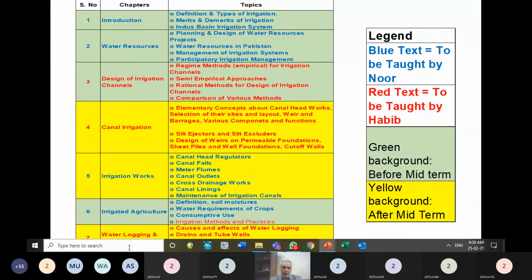So in this part on the tube well, we will be telling you the construction of the tube well. What are the components in the boreholes, the pipe, the screen, the shrouding around it, and so we will be talking more about the construction of the tube well instead of the calculation of the discharge for a tube well.